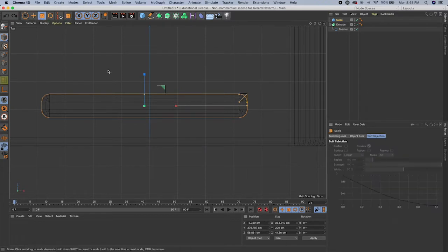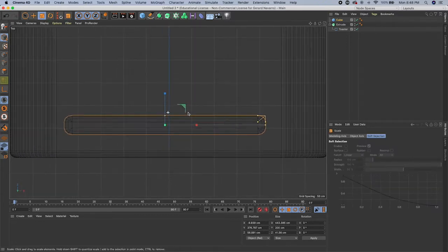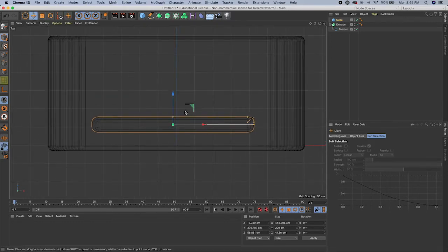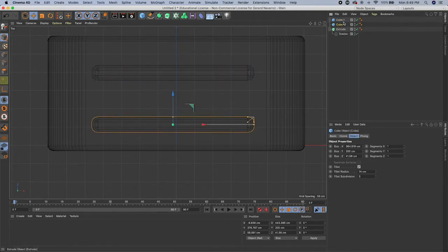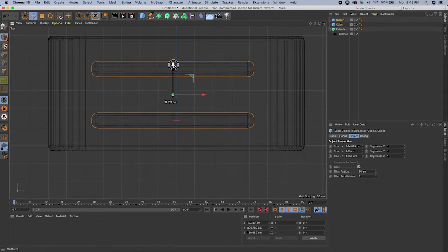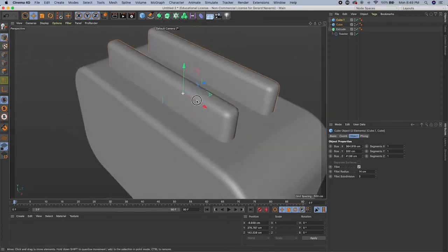And then let's align it. And then let's also scale it lengthwise. And then let's duplicate this one. So I'm going to hold down Control or Command on my keyboard and then left click and drag. So we now have both of our toast holes aligned here.